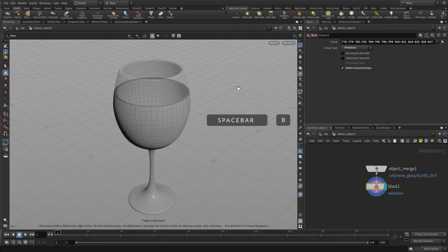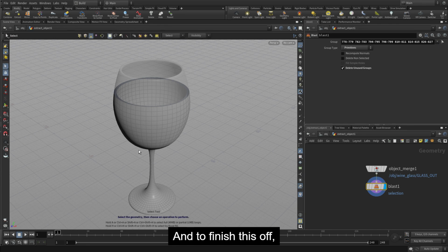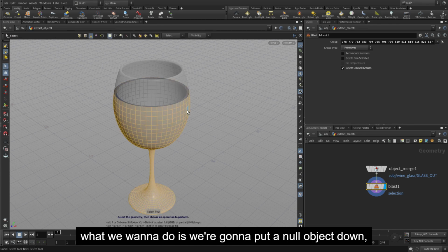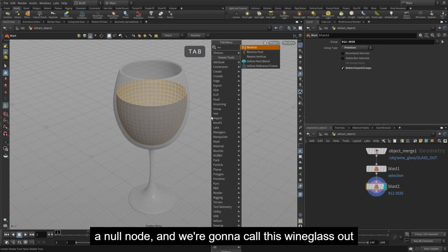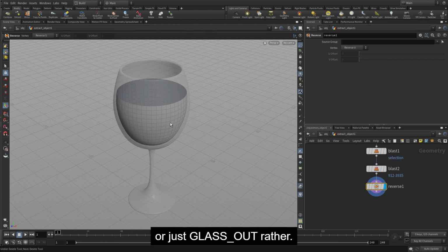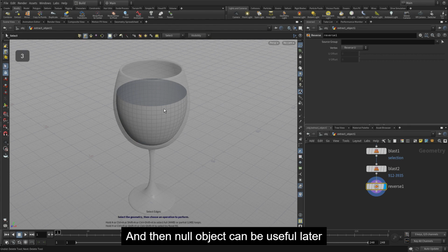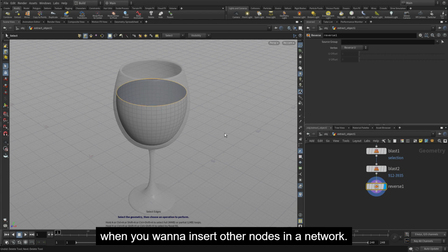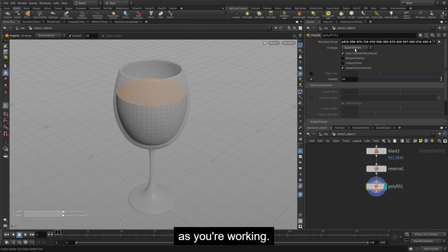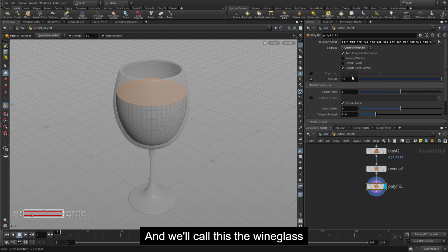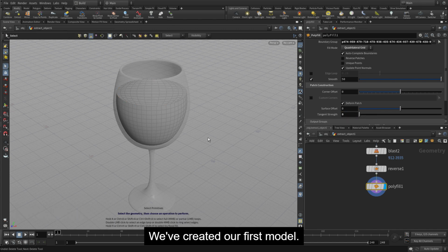If we go spacebar B and bring back this view here, we can then double click on the outer edge and delete everything there. So we get 2 blast nodes, and they get rid of everything except inside. Add a reverse node because the normals were pointed in the wrong direction. And now we can double click on the top of there and do a tab poly fill. To create a nice topology for that, we're going to go quadrilateral grid, and we'll do a tangent strength of 0, and that puts a nice, just sort of a flat surface there.